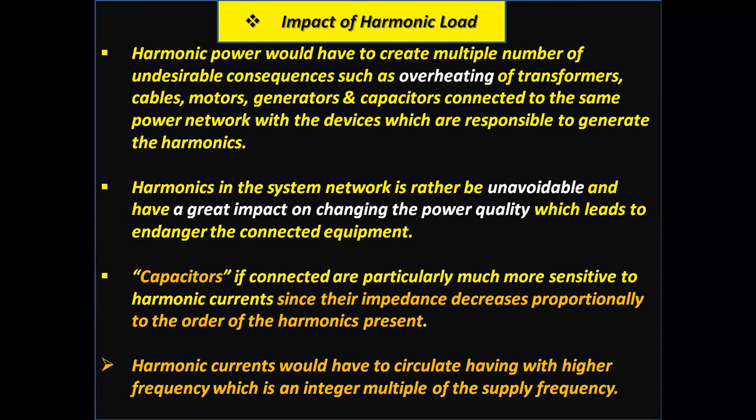Capacitors, if connected, are particularly much more sensitive to harmonic currents since their impedance decreases proportionally to the order of the harmonic present.